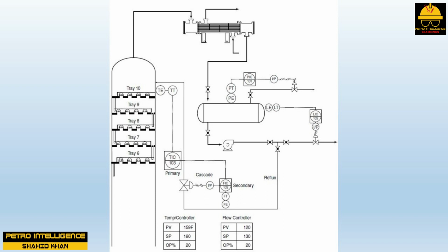In many process systems, it is possible to accomplish a variety of similar objectives simultaneously. For example, in a distillation system, reflux is used to control temperature and improve product purity. In most cases, a flow control loop is used to ensure steady flow. However, temperature control is considered to be the single most important factor in this system.